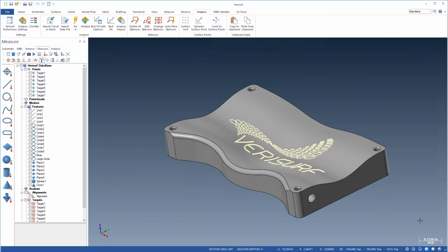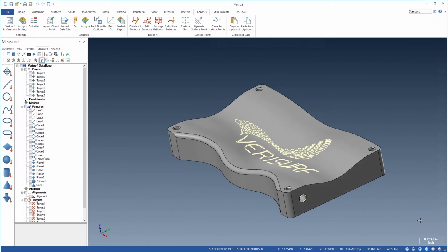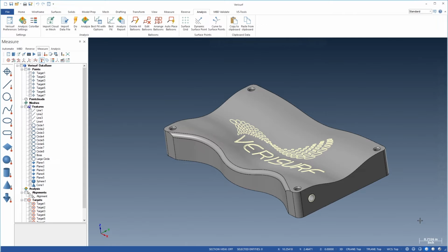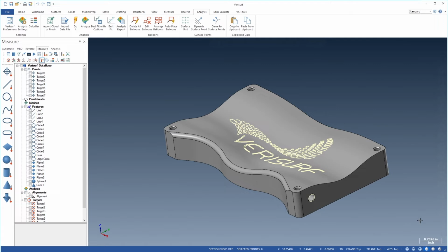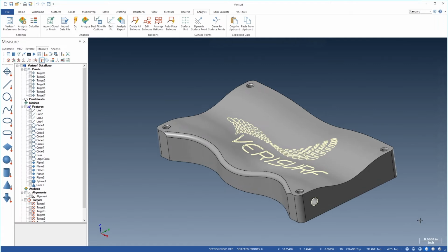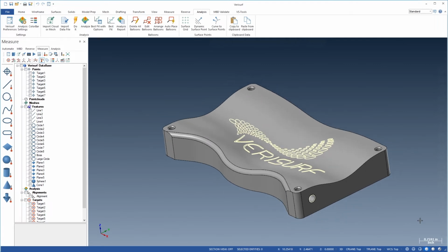If we use the Alt key in combination with the arrows, the left-right keys rotate the model at its centroid, around the screen's vertical axis, and the up-down arrows rotate the model around the horizontal axis. Finally, we can press Page Up to increase the zoom, and Page Down to zoom out.